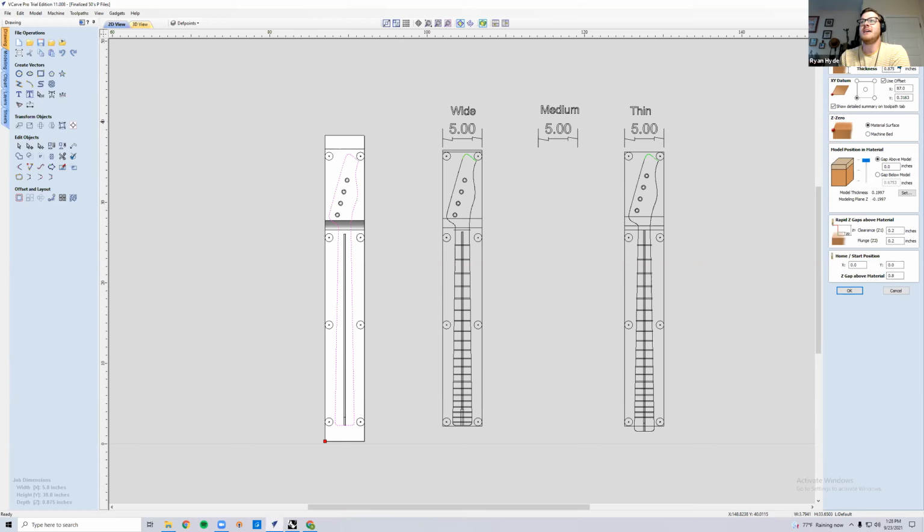So in this, I can tell it the thickness. I can tell it what corner of the CNC to start in. You can pick different corners. The Z0 is really important because that tells the machine where to calculate its height and therefore how far it drills.